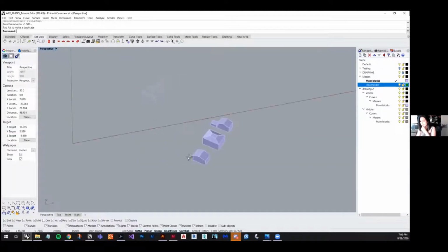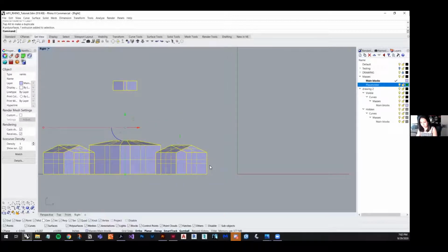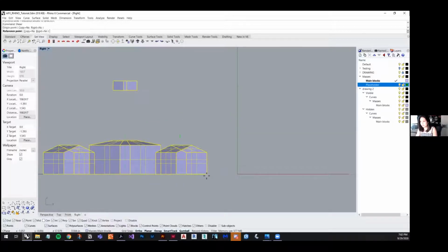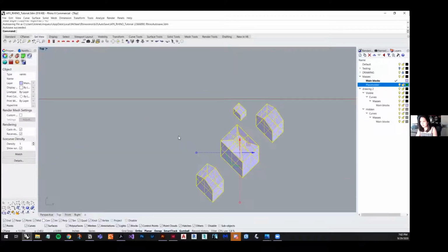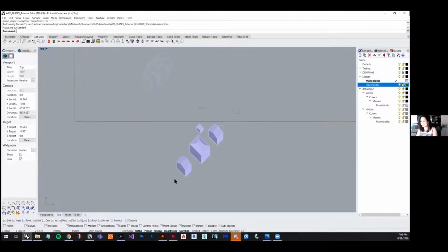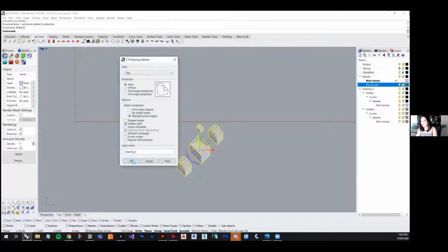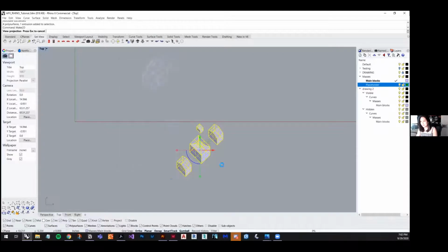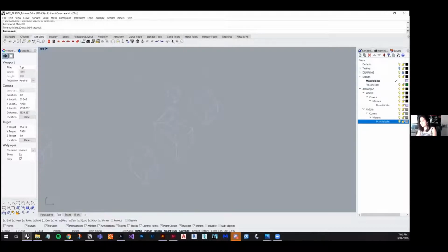There you go. So if you did the very same thing that we did, this is already turned in 45 degrees, but if we selected our objects that we wanted to shear, did shear again, took from the corner, and then did -45, in top view it's already an exploded axon. So when you make 2D with that, you can do it in the same one. It'll keep it nice.